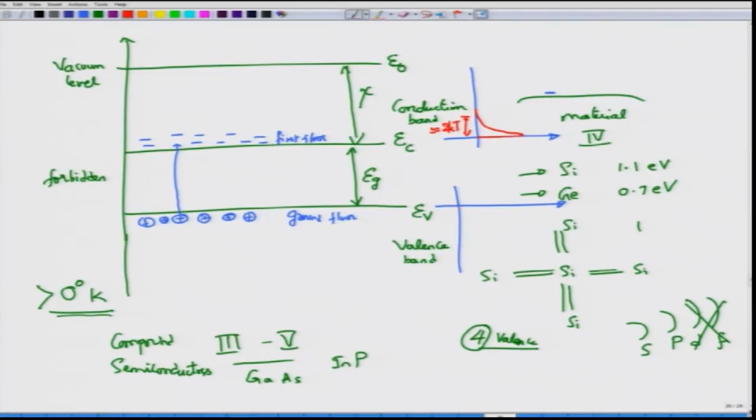So, if you look at the concentration of the holes, it will again be quite large at the band edge, and then drops out with the width being typically about 2 kT. So, after 2 kT there are almost no free holes here, and about 2 kT from EC there are almost no electrons. So, this is just an example of electrons always hugging the bottom of the band, whereas holes always float to the top.